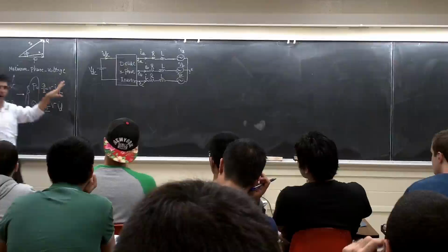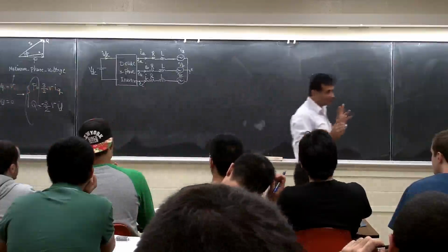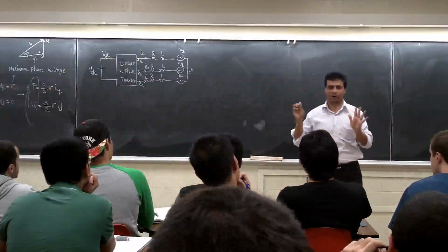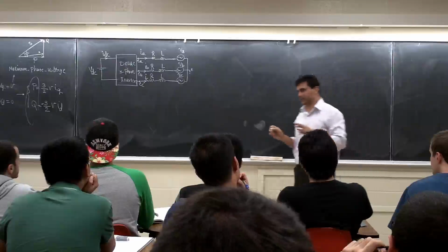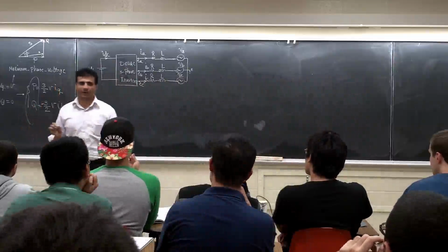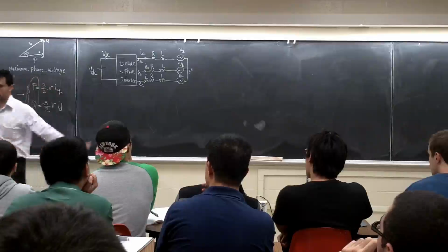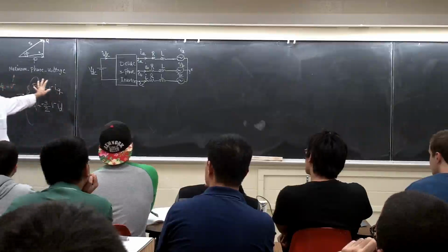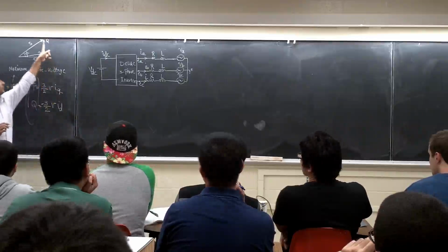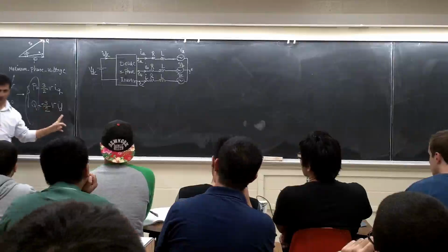But there are some devices. They call it SVC, static var compensator. They are designed to inject Q or absorb Q. There is no power, P is 0 for those ones. On that one, they are different. We use them for power factor correction, and we use them for voltage support. But in this course, we want to keep it unity power factor. Unity power factor means Q is 0, right? So Q 0 means Id is 0, right?